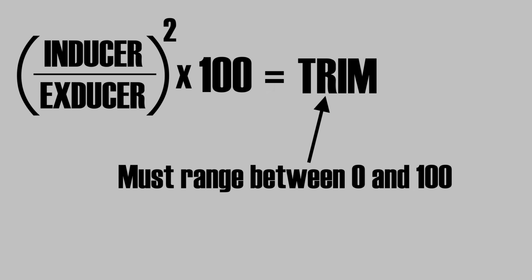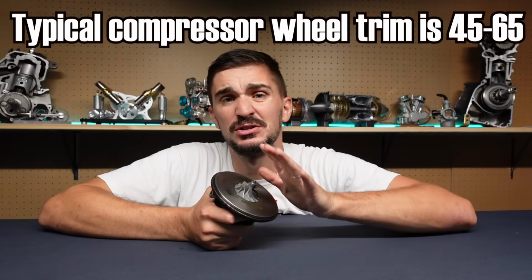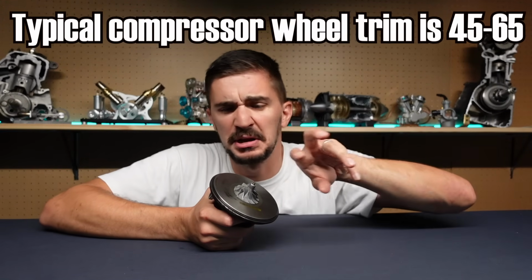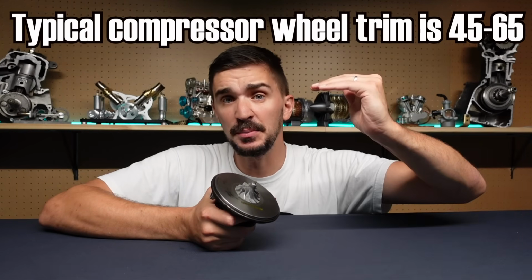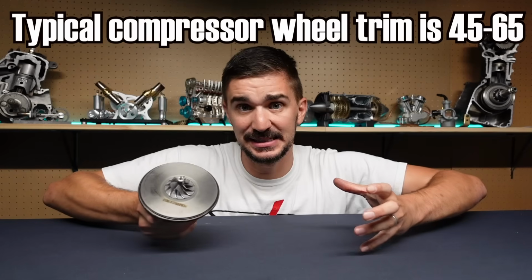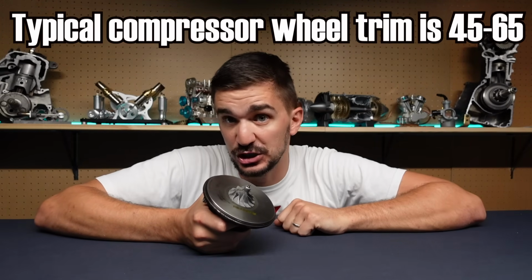However, you will never see 100 on an actual turbo because that would mean that the inducer and exducer are of the same size and that wouldn't work at all. In reality, most compressor trim numbers are somewhere between 45 and 65. There are exceptions, of course, but most are in that range. A higher number means that we have increased maximum airflow capacity, so increased peak power, at the expense of an increased boost threshold.